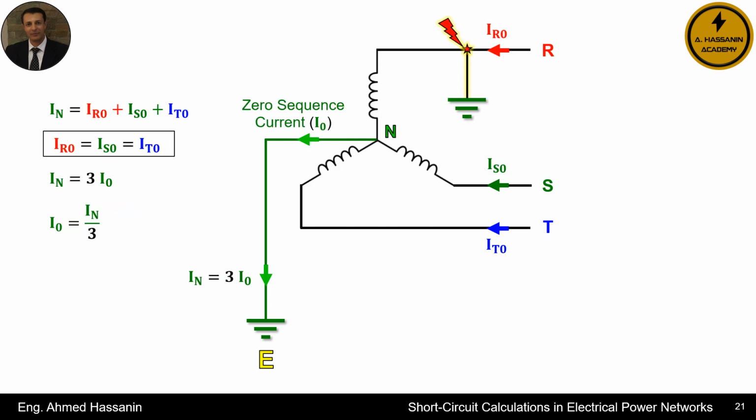As for the zero sequence current, it is indeed the current that flows through the neutral line, but only under the condition that it flows during unsymmetrical earth faults, whether it is a phase-to-ground fault or a phase-to-phase-to-ground fault. The second point is that for zero sequence current to appear, the neutral point must be grounded. Therefore, we emphasize that the only situation in which zero sequence current appears is during unsymmetrical earth faults.